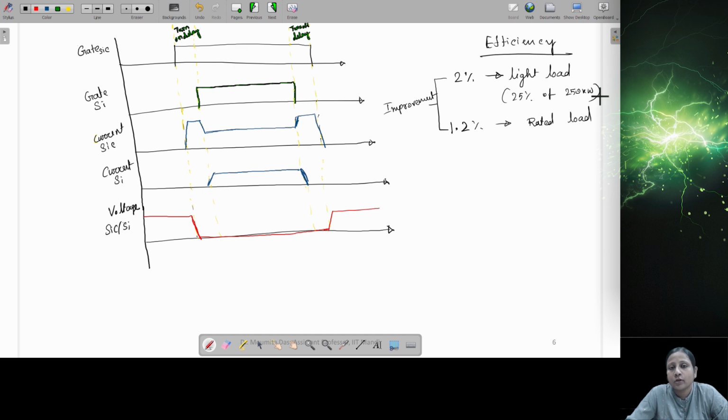The same converter prototype, only the switches are changing, and also the gate signals, where we need to give some delay time. Other than that, everything remains the same. Even in this hybrid condition we are achieving some efficiency improvement. If we can go for complete wide bandgap devices, by solving this EMI, dv/dt, di/dt problem, then the efficiency improvement will be much higher. Obviously this is much more beneficial for renewable energy applications, right?